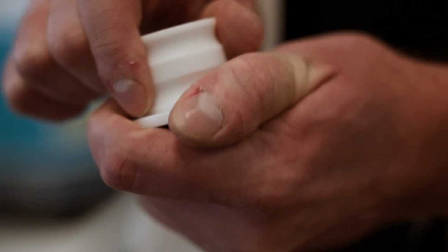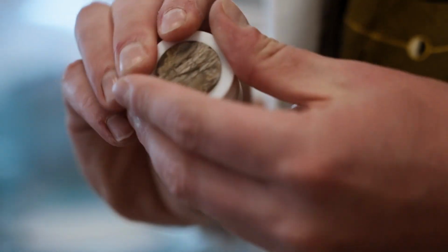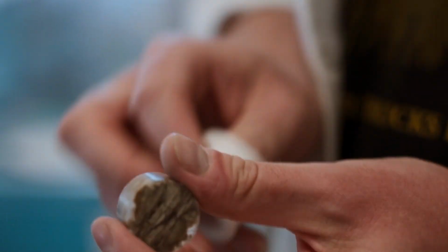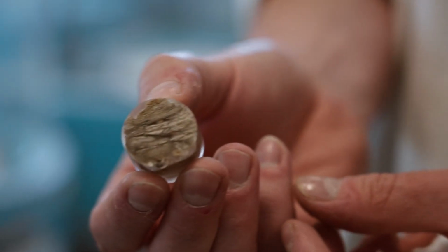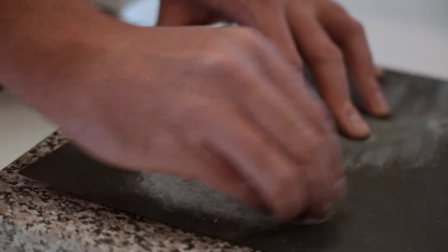We've now embedded the specimen in resin and the resin's cured. So now the next thing to do is to polish it on finer and finer grades of sandpaper to get a really nice surface finish for the microscope. We're now starting to see much more internal detail inside the rock than we could see before we started preparing it.